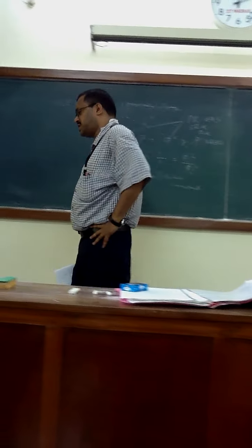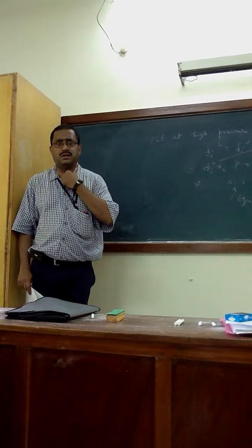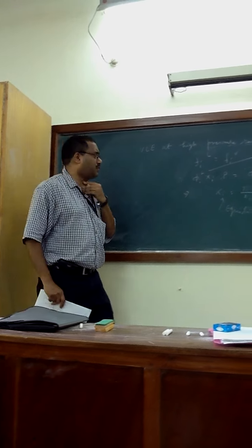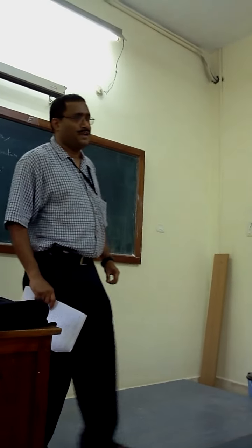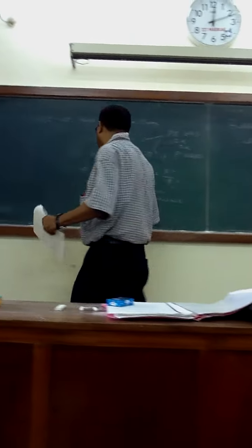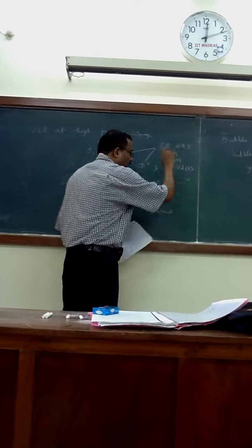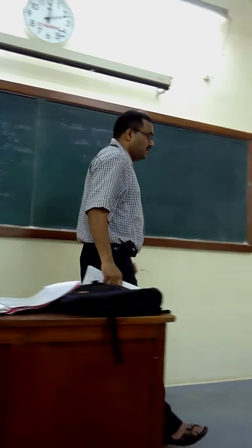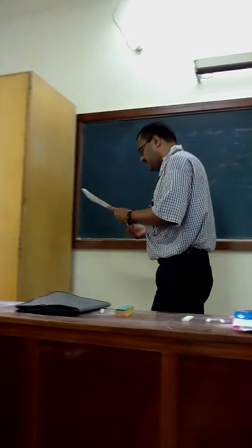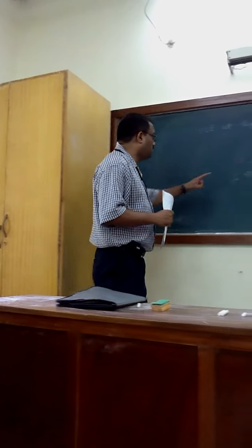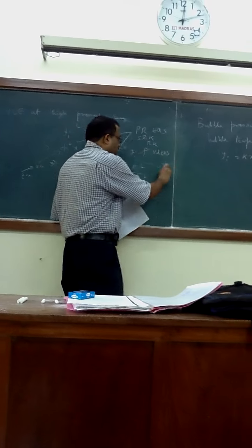So how will the algorithm work? If I have high pressure, we have to solve for the fugacity. Remember that the fugacity formula is the same for the liquid and vapor phase. And why will the fugacity values be different? Because VL is not equal to VV. phi_i^L will have VL and phi_i^V will have VV, and with that they will be different. When we calculate the fugacity, you will see that fi^L is not equal to fi^V, because we don't have VL directly, we have ZL. Remember the formula has Z.